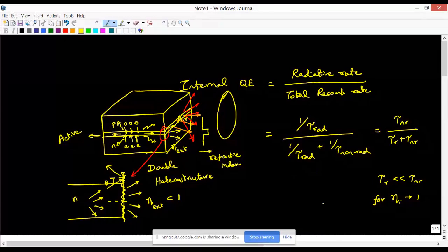So I think we derived this formula to be eta external equals 2 over n multiplied by n plus 1 the whole square. And in GP Agrawal, somebody brought to my attention that it's mentioned as 1 over n into n plus 1 the whole square. So they were wondering, why is there a difference in the formula?